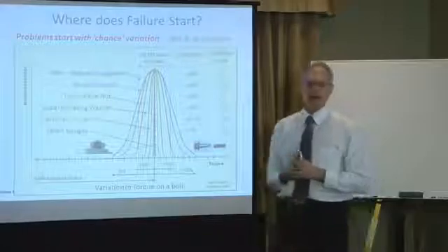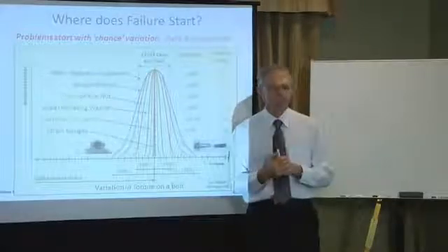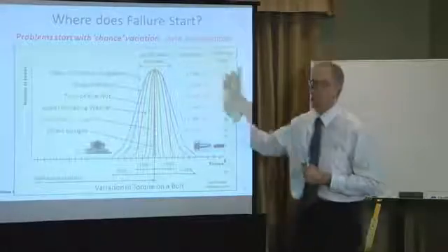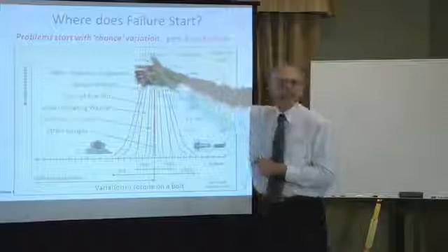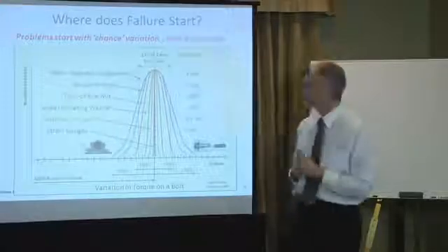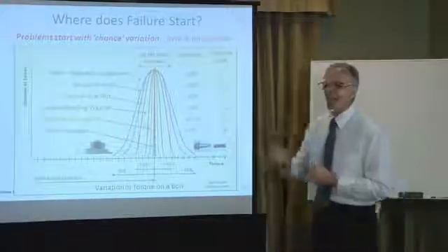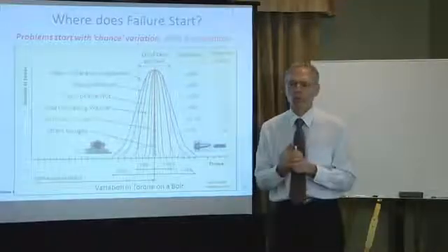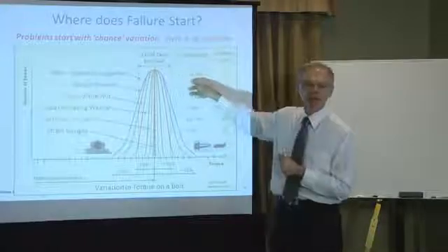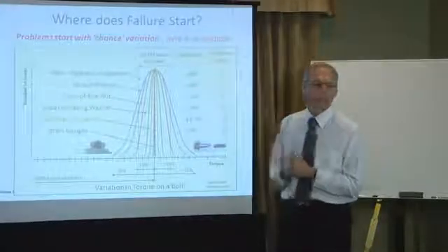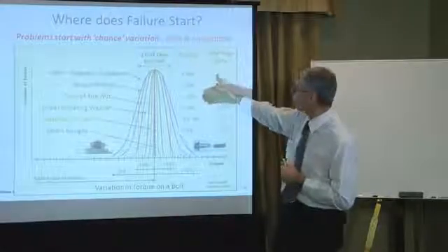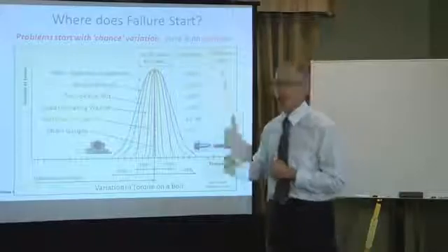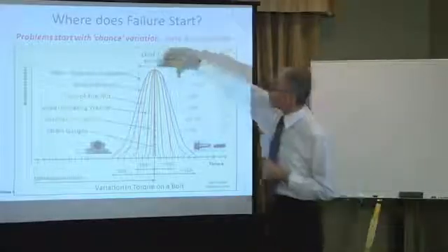So in my business, I've got to be very careful what process I choose, because the process delivers the outcomes. It isn't the people in the process. It is the choice of the technique and the tool that delivers the outcome. So if I have a process where I cannot allow my fasteners to be improperly fastened, they've got to be at the right tension and torque all the time, I can't use muscular feel. Muscular feel will guarantee failures every now and again. I've got to go to something like turn of nut or load indicating washers. And if I don't choose those, I can never get those results, except by luck.